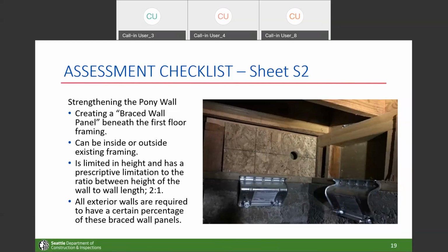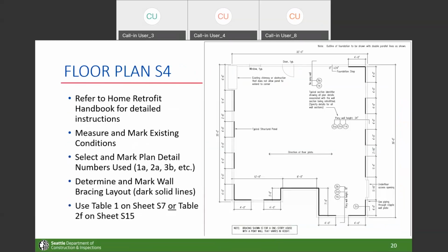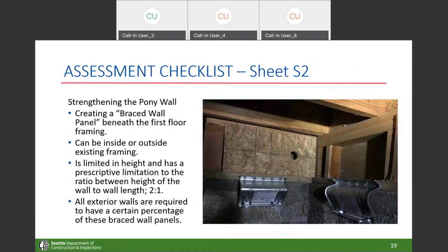How are things going? Jeff had a question about that anchoring procedure. Jeff, can you repeat? Let me see if I can find his question. Jeff has a 1955 house with a basement, 8-inch poured walls with non-secured 2x4 pressure treated plates. Looking at the Simpson hardware, this requires 2x6 on an 8-inch wall. Is there an approved detail with a PT spacer block?